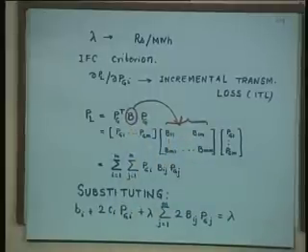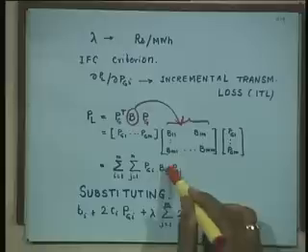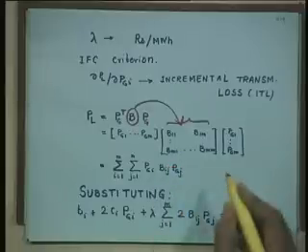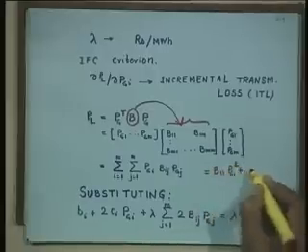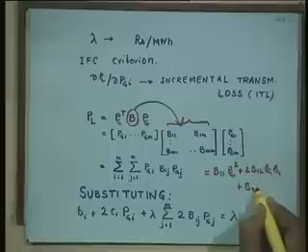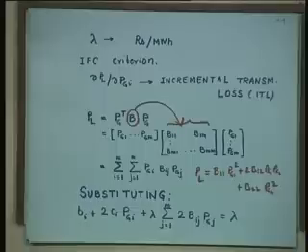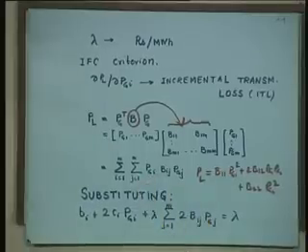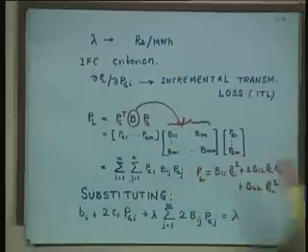Those of you who have studied linear algebra or control systems know about the quadratic form. If you want to write it in index form, two summations, i from 1 to M, j from 1 to M, PGi Bij PGj. If it is a two plant system, then the answer will be B11 PG1 squared plus 2 B12 PG1 PG2 plus B22 PG2 squared. This will be PL for a two plant system. That is the expansion of this. If it is 4, maybe a whole sheet is required to write that equation. So these are the three different ways in which you can write it.